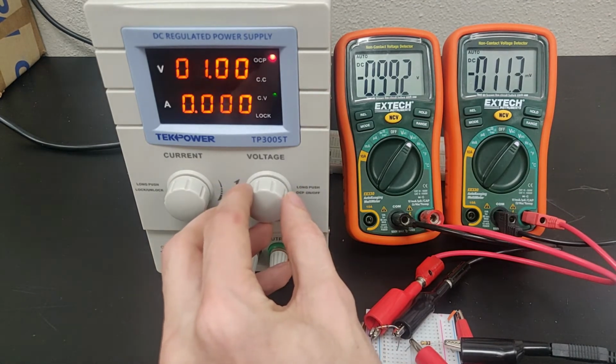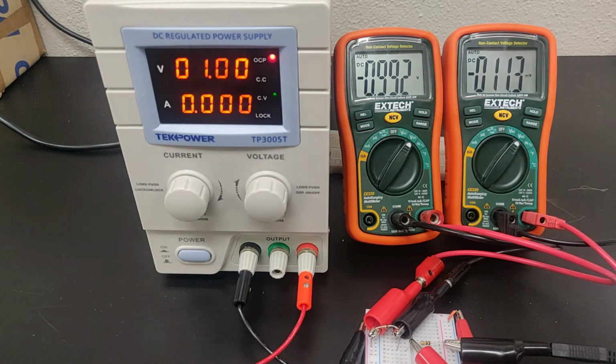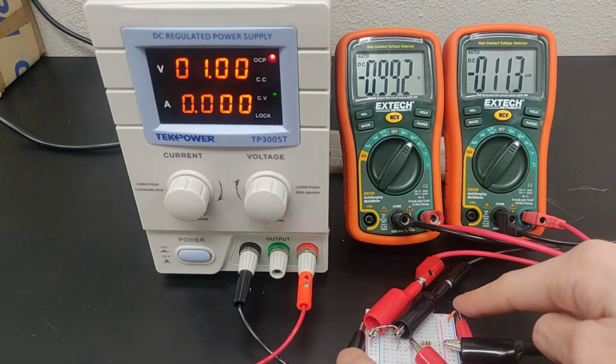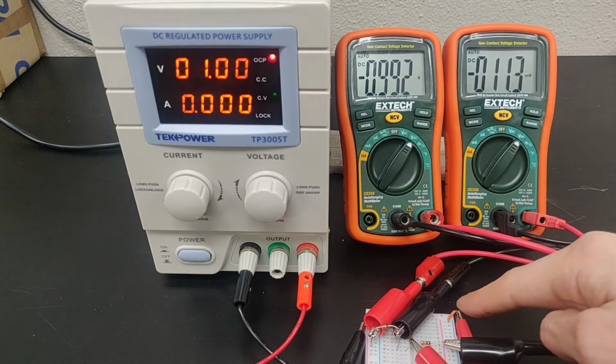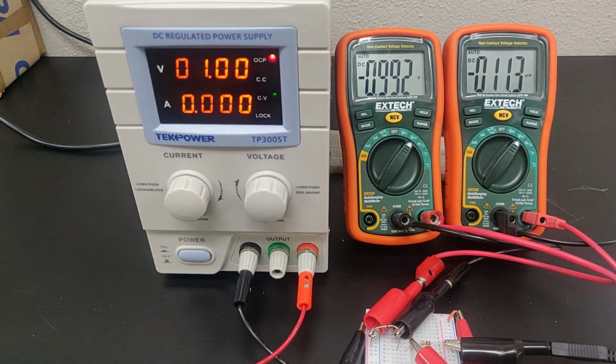So first one. Oh, I'm sorry, and one last thing. The values are going to be negative again, because one, it's going to be our reverse bias plot, so our value should be negative, but also the leads are set up in the same way that I had it for the reverse bias for the signal diode, where I switched the leads while keeping the alligator clips for the multimeters in the same orientation. So we're getting negative values, but that's fine, because that's what we want.